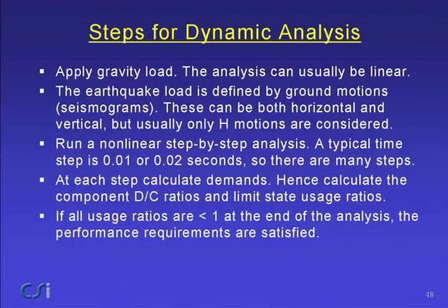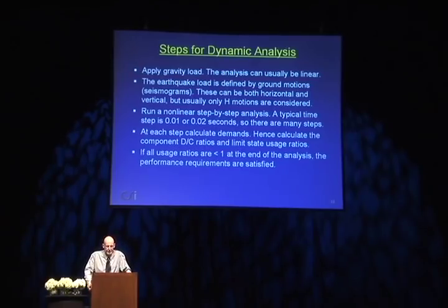In some cases, incidentally, the capacity may also have to be calculated at each of these time steps, because sometimes, for example, a hinge rotation capacity can depend on the shear force of the hinge. The larger the shear force, the smaller the ductility, the smaller the rotation capacity. And since the shear force varies during analysis, you have to recalculate the capacity at every time step also. And Perform can do this.